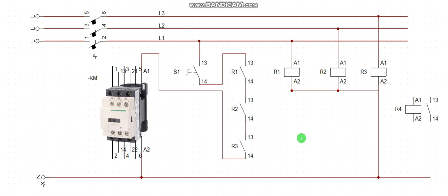Okay, today we are going to discuss a relay called phase failure. Phase failure relay. Some challenges we used to encounter when we go to a remote area to carry out our job: we cannot access some of the components. So if you discover that while carrying out your job the phase failure is not working, and you have some normal mechanical relays at your disposal, you can use them to form your phase failure, okay?